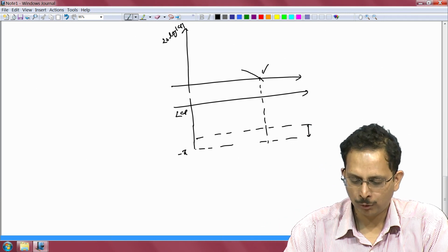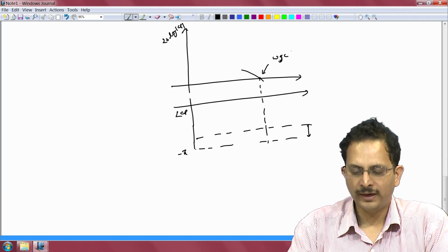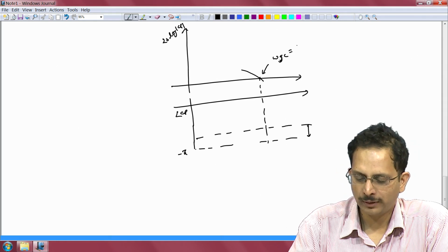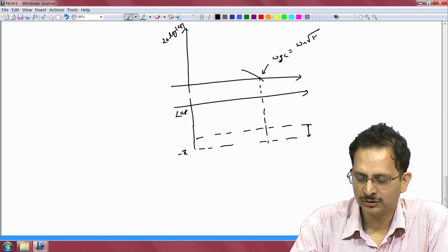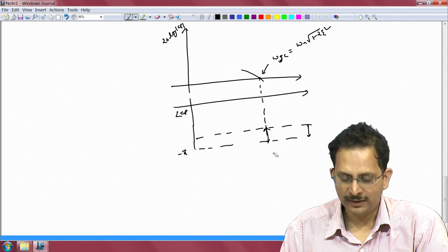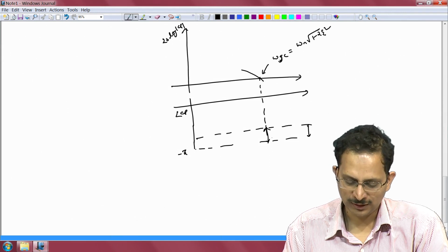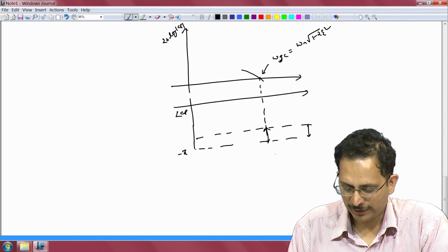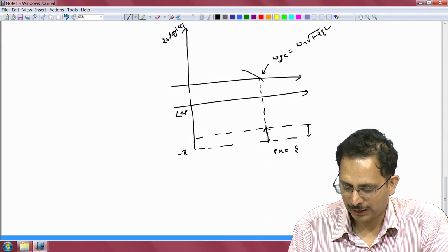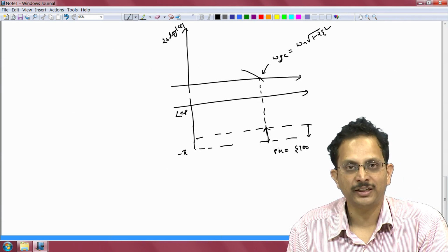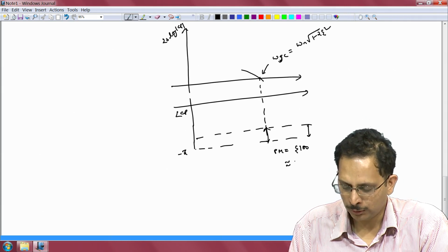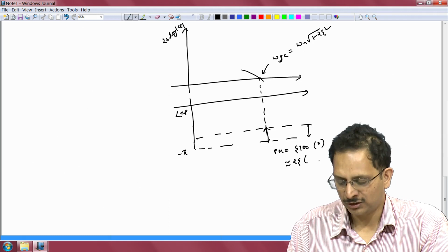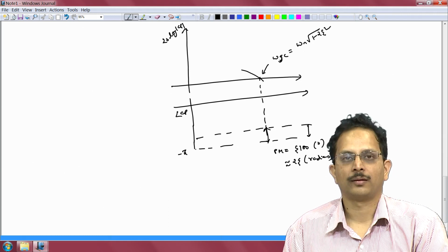We note that our omega gc can be obtained if we have specified the rise time and the damping coefficient as omega gc equal to omega n square root of 1 minus 2 zeta square, and the phase margin, which is the difference between minus pi and the phase of the plant, to be related to zeta as phase margin is equal to zeta times 100 when the phase margin is represented in degrees, or is approximately equal to 2 times zeta when the phase margin is represented in radians.